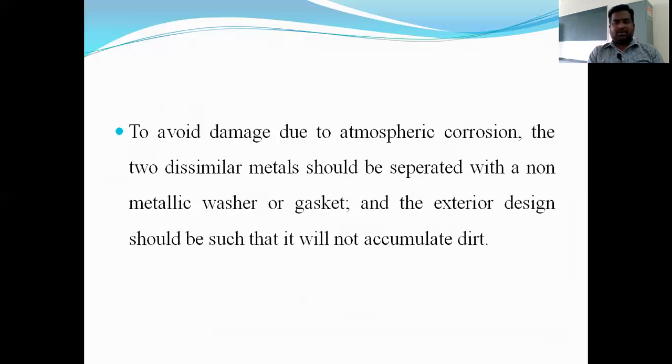The two dissimilar metals should be separated with a non-metallic washer or gasket, and the exterior design should be such that it will not accumulate dirt.